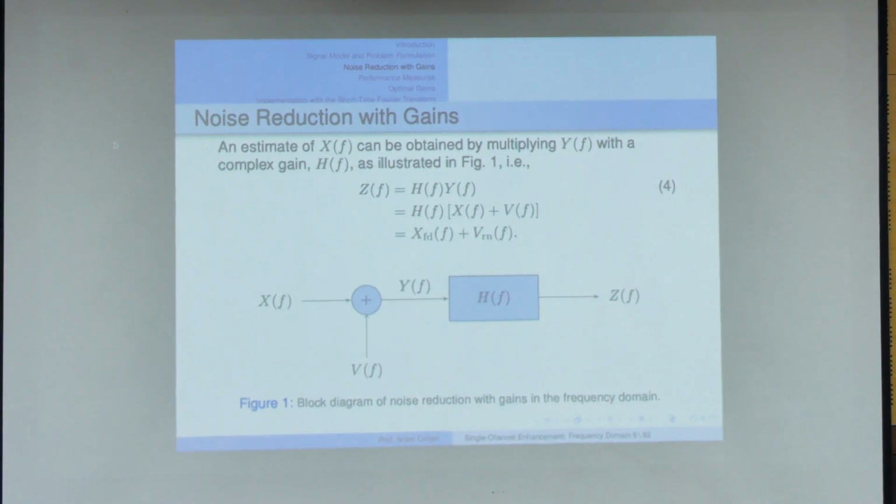So the distortion using a gain like that will come from weak or low SNR frequency components, okay? Because when we have a gain like this, of course we will put low gain in frequencies where the SNR is low, to minimize the distortion of the desired signal. Okay, so all this makes sense. Let's continue. If you have any question, please ask, okay?